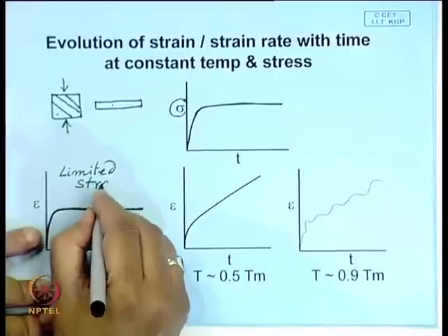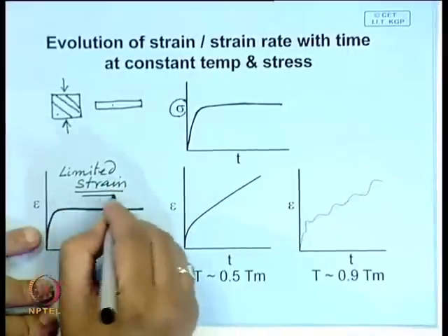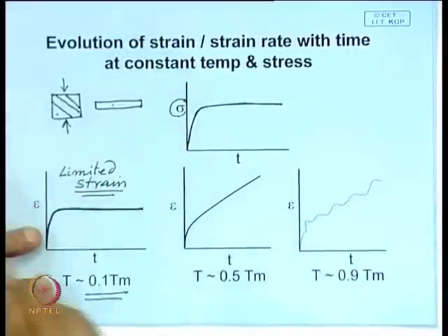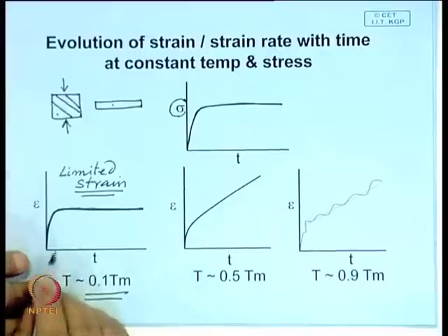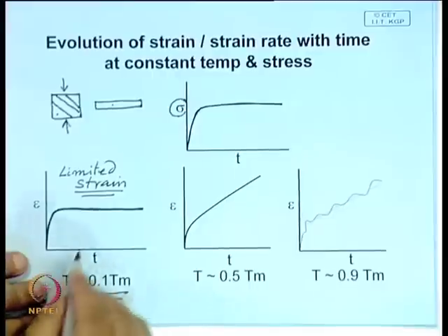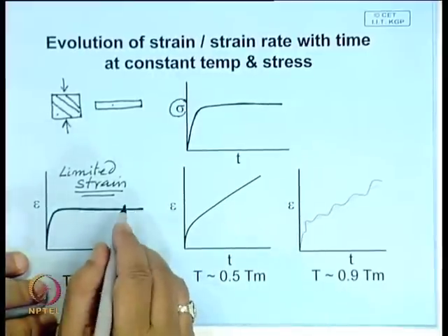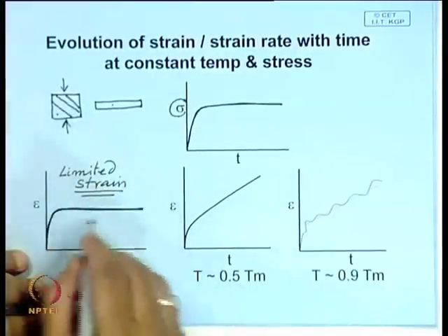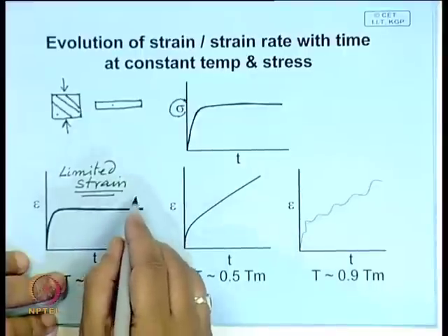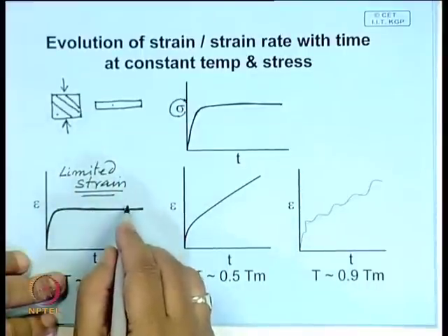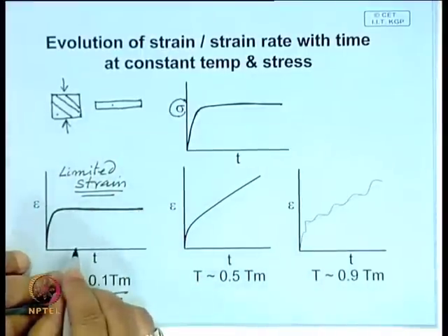The material hardens, and therefore, you cannot strain it further. To give a further deformation, you have to give an intermediate treatment to restore its initial structure and bring down its strength. So, give it an annealing treatment, then only you will be able to deform.